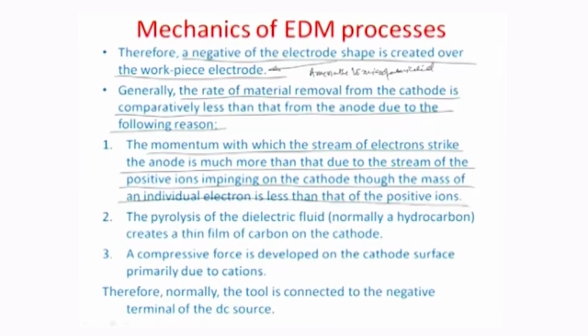So, what is a spark? It is essentially a breakdown of the medium, and once the electrons are generated from the cathode side and come out of the cathode, they are free electrons, and they would create a lot of collisions with the medium particles which are there in their path, thus creating ions and more electrons. So, in principle there are two different kinds of electrons. One is the primary electron which is emanated from the cathode, and another is the secondary electron which comes because of the collision of those primary electrons with the particles of the medium. Okay. So, therefore, it is really an avalanche on the electron side.